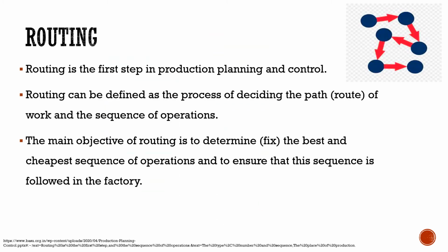So the next concept is routing. So what is routing? Routing is the first step in PPC. The name itself indicates routing means path or route. So routing can be defined as the process of deciding the path or route of work and the sequence of operations. So routing fixes in advance.